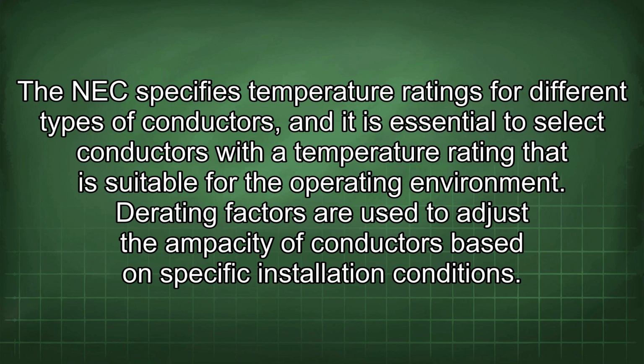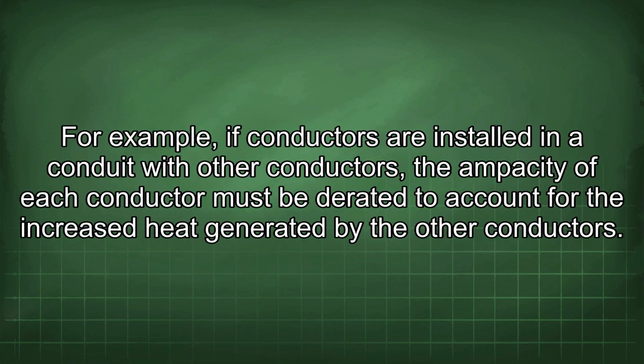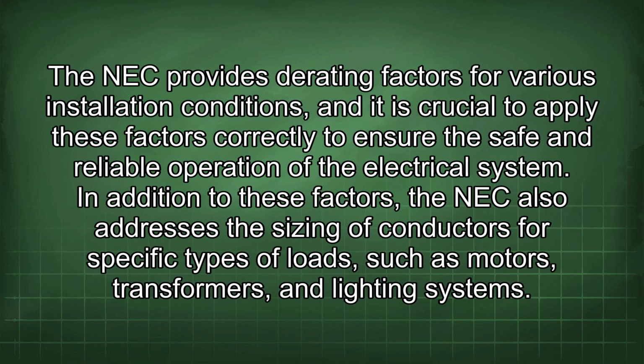Derating factors are used to adjust the ampacity of conductors based on specific installation conditions. For example, if conductors are installed in a conduit with other conductors, the ampacity of each conductor must be derated to account for the increased heat generated by the other conductors. The NEC provides derating factors for various installation conditions, and it is crucial to apply these factors correctly to ensure the safe and reliable operation of the electrical system.